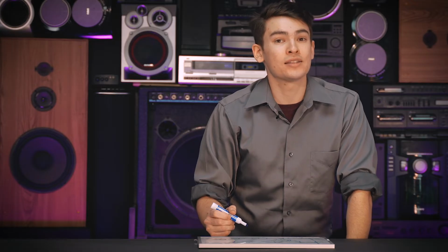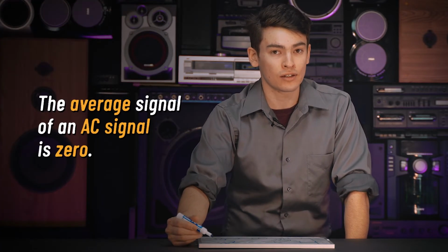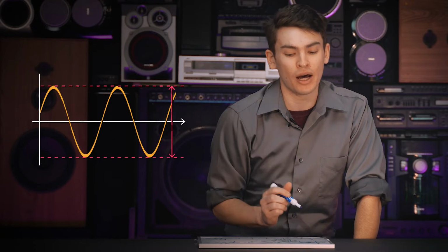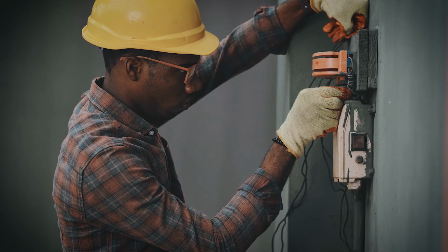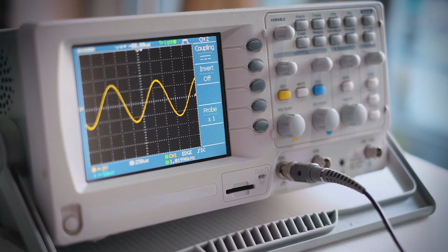That's not to say that it is the average signal though. The average signal of an AC signal is 0. The positive peaks always cancel with the bottom peaks. They alternate and they're always equal. RMS voltage is generally used to measure most signals. In fact, unless otherwise stated, it's a good bet to assume you're measuring RMS voltage. Most meters and oscilloscopes will have the option to either switch between them or it'll be measuring RMS by default.